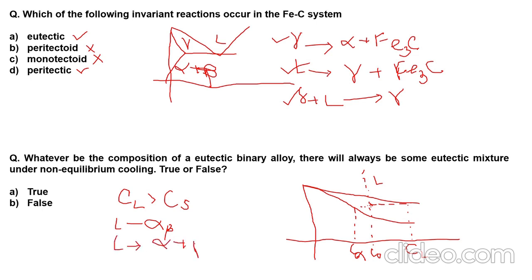So because of faster heating rates, there occurs one difference in the non-equilibrium cooling: you have a compositional gradient in your mixture. Once your mixture is solidified, for example a bar, it will have a compositional gradient. It will have C1 in the region that quickly transformed, and another region with composition C2, which is different from C1, because you did not allow the mixture to diffuse correctly or allow homogenization. As a result, there is always a compositional gradient in the system.